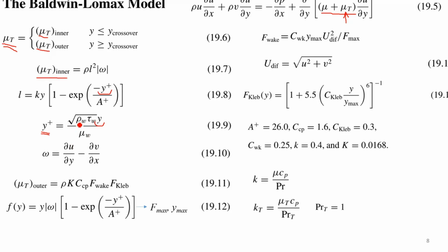These parameters here, rho w, tau w, and mu w, are also functions. For compressible flow, we know that density changes from one point on the wall to another, and shear stress is proportional to the velocity gradient. The viscosity on the wall also must be defined. It could be defined as constant, but also could be defined as a function of the quality of the surface.